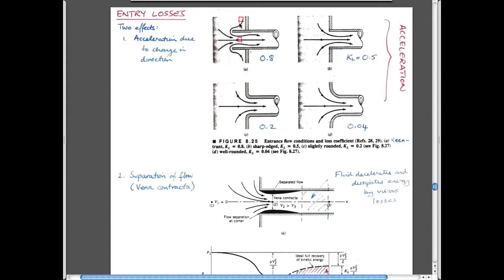And so, again, like when we talked about Venturi flumes or Venturi pipes, if you have the smoothest Venturi flume, you have the smallest loss because you don't have any flow eddies developing that eat up all your energy and dissipate as heat. If you have a more disruptive fitting versus a really very straightforward fitting, then you could imagine that the loss in the system is larger where it's more disruptive. Less disruptive, at least you don't have a protrusion into the tank, so you don't have to go around here. You can physically go directly from here to here.